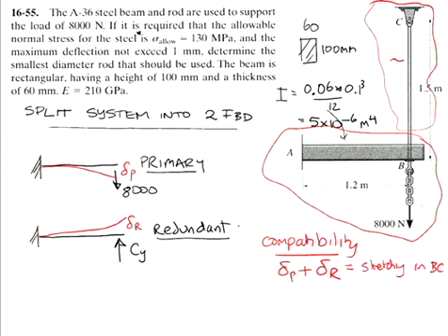And what is the stretching in BC equal to? Remember the formula from way back? The amount of stretching here is equal to PL on AE. So therefore, this is all equal to P. And what is P? Well, it's the force, CY, times L on AE. So this is our PL on EA. Is everyone clear with that about that?